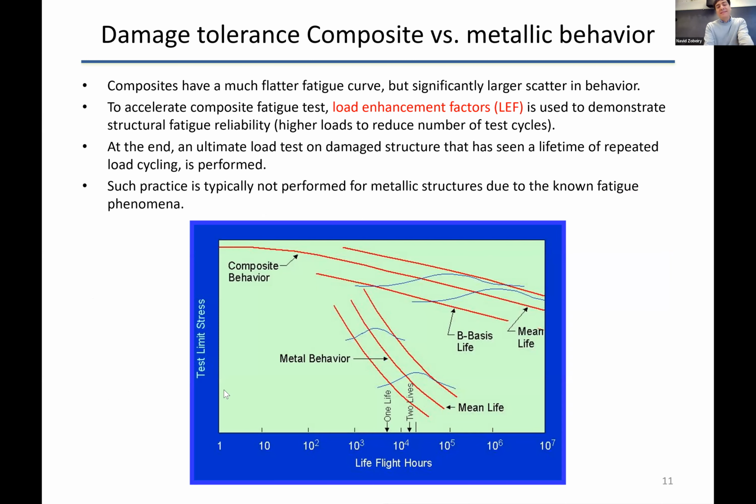Let's say you're doing a fatigue test, and on the x-axis is the cycles that you do. And on the y-axis, let's say you are plotting the strengths of the material, but you're not doing one test, you're doing multiple tests. Let's say you have done 1,000 hours of flight time simulation on the material. So on the mechanical and the hydraulic testing frame, you place the material and they go back and forth, back and forth, back and forth, and you measure the strengths after 1,000 cycles.